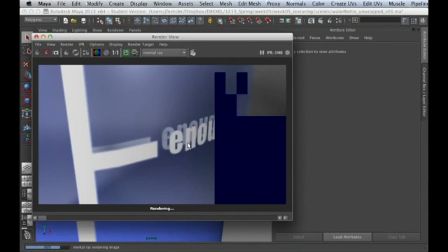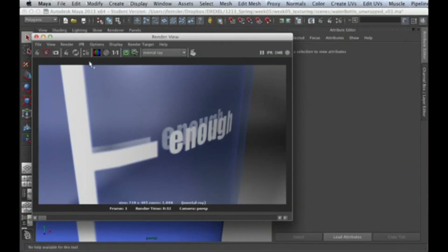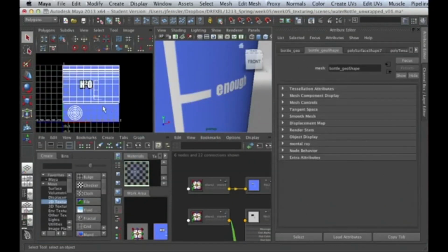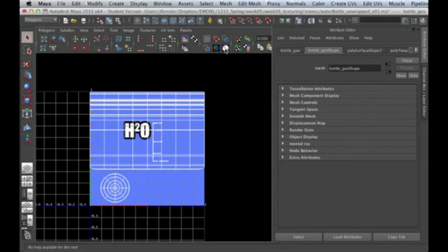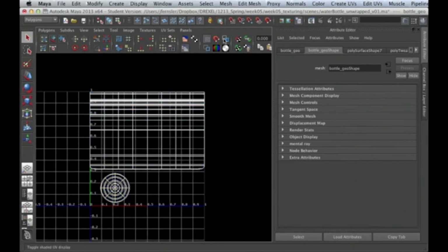We looked at our UVs and they looked pretty good, but clearly our UVs are overlapping here. Okay, and let's close this out and we'll pop over to our UVs. I'm going to turn off my texture here, or at least, I'll just remove it. I'm going to turn on my shaded view using this selection here. Aha, there we are. Everything looks purple, which means that somewhere under here is a red and a blue mixed together. Blue being proper and red being reversed and overlapping, right?